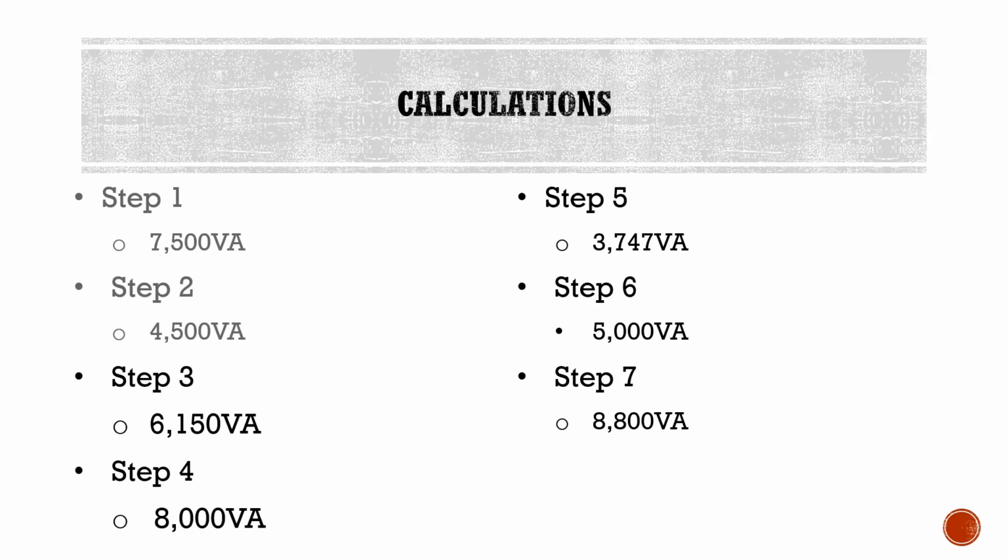Now this is where I see the second place that a lot of people mess up on this calculation. So we look at our answer here for step number 8, we get 174 volt amps. Now if you paused and did that calculation ahead of me, or you pause now and do that calculation, you may initially be a little bit confused, because this is not 125% of the FLC of that quarter horse 120 volt motor.